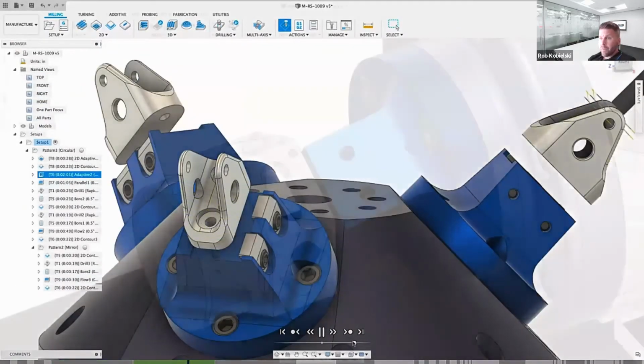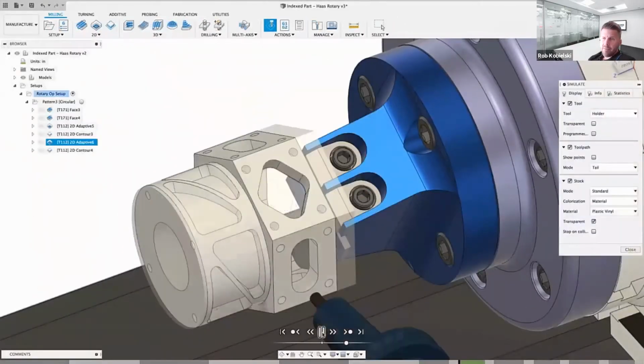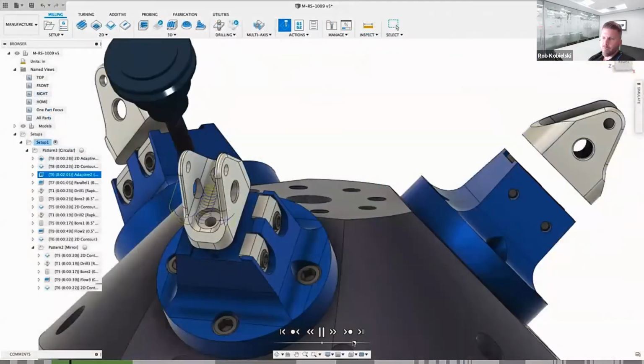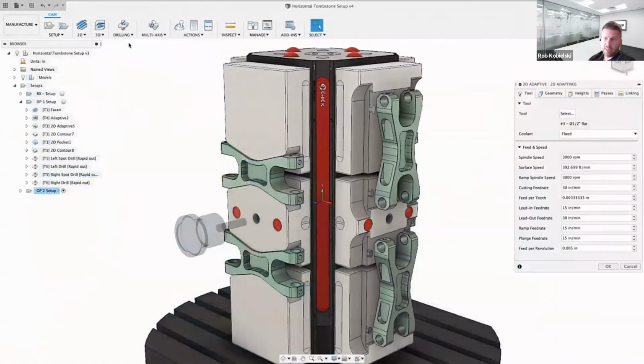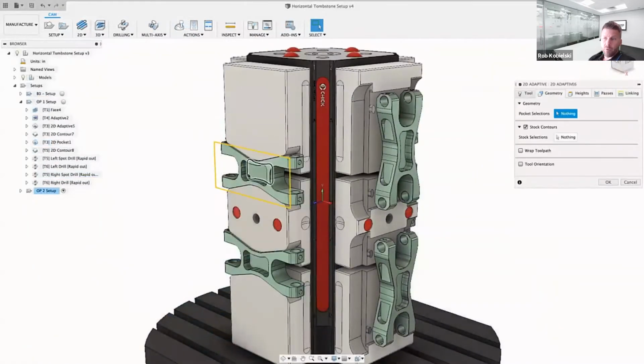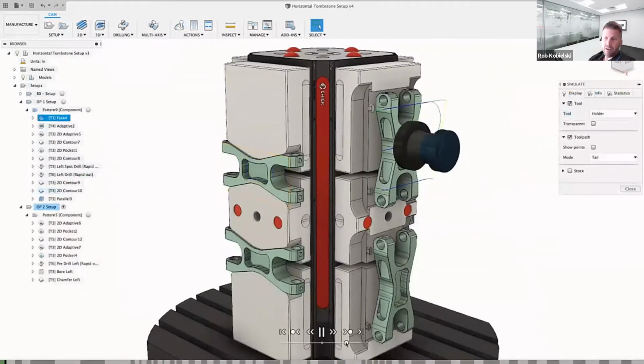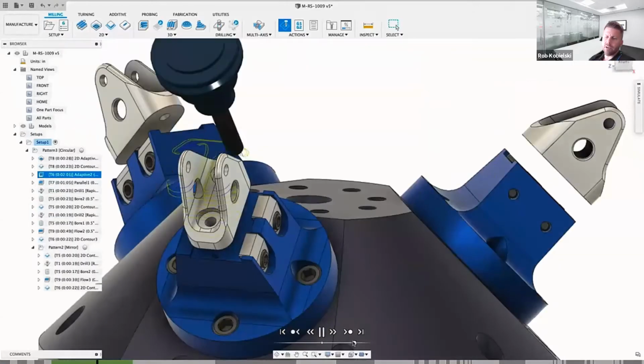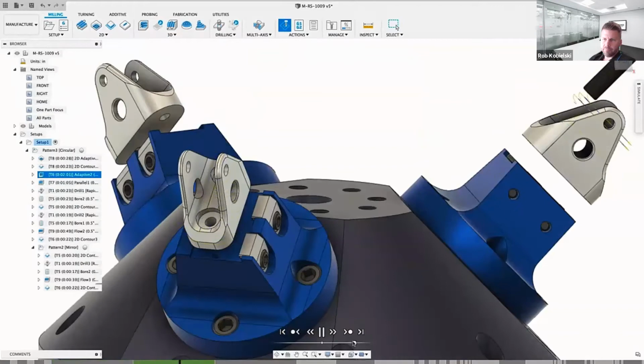To reduce the cost of fixturing and produce parts in fewer setups, multi-axis positional machining such as 3+1, 3+2 can be used. Toolpath directions can be rapidly selected and calculated with efficient ordering options for multi-part machining on tombstones.